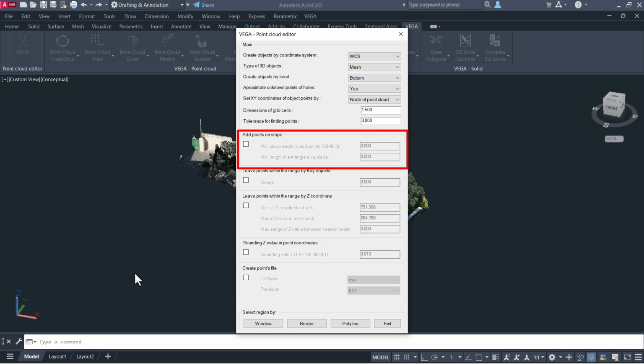The parameters that we're not going to change are covered in the Basic Parameters video. Now we are going to use additional filtering. Height filters, which determine which points to consider when creating a mesh, and which to filter based on their z-coordinate. By default, we have the minimum and maximum values of the point cloud height. There is also an additional filter that filters out nearby points. For example, if the height difference between two close points is less than 10 centimeters, only one point is taken. We will not use it now. The only parameter we have changed is the maximum height.